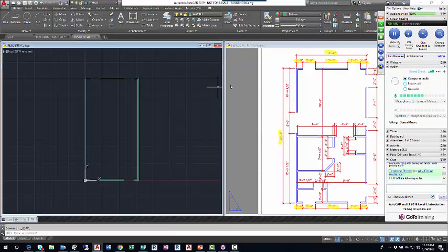So there's no wrong next step, right? I've started working on exterior features like the window openings. I'll just move forward working on exterior features, the window openings, which will be, I have the 1'6" and the 3 feet at the top, and at the bottom, same thing as the windows in the horizontal wall, but it's a vertical wall now. So I'll go offset, I'll just type in 1'6" and hit enter.